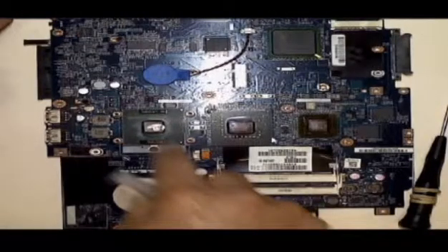Another great tip that I can recommend, guys, is to apply thermal materials. If you can, watch my other video on how to apply thermal paste and thermal pads on specific components. Please do so, because I have detailed how to do it, and it can also prolong the life of your CPU as well as the video chip.